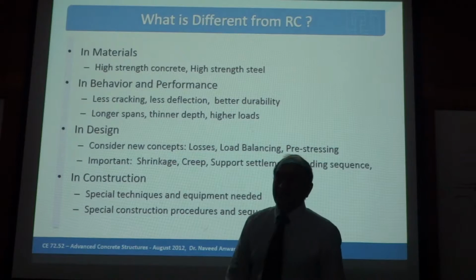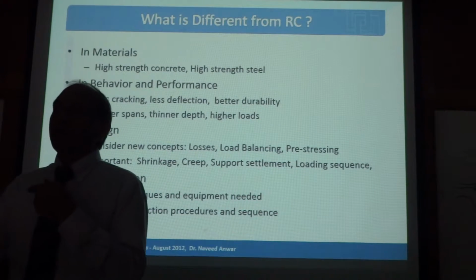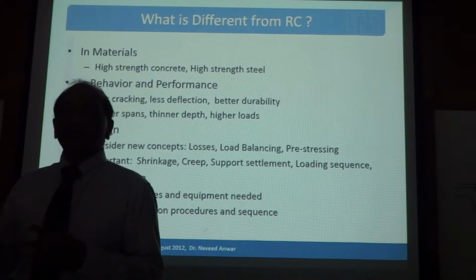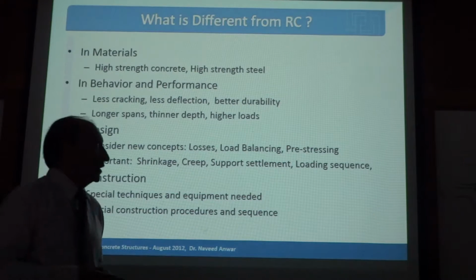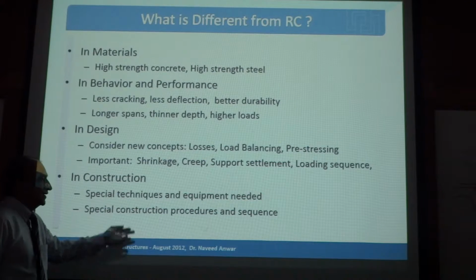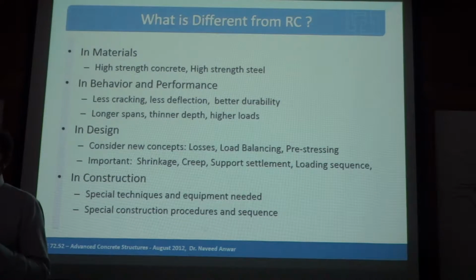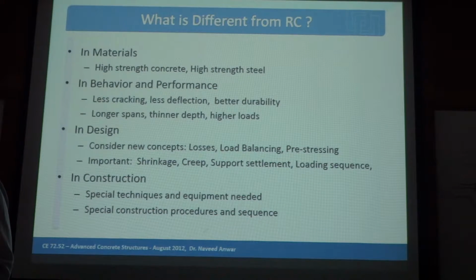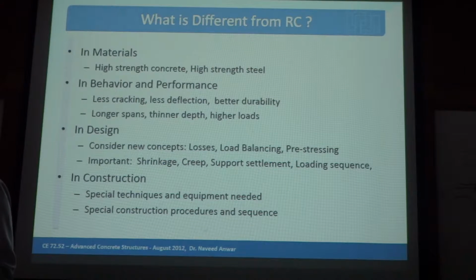So it acts before the loading is coming in, and that creates this loading sequence problem: when to apply the loading and when to apply the pre-stressing, because now you have to do it before the loading comes in. Loading comes in many steps, in many ways, in many directions. So how do you pre-stress it at the right time? Sequencing is very important. In construction, there are special techniques, special equipment, special procedures and sequence. It's highly technical construction. Not everyone can do it. Few people know how to do it well. Very few companies have the capability, both for the design and construction.